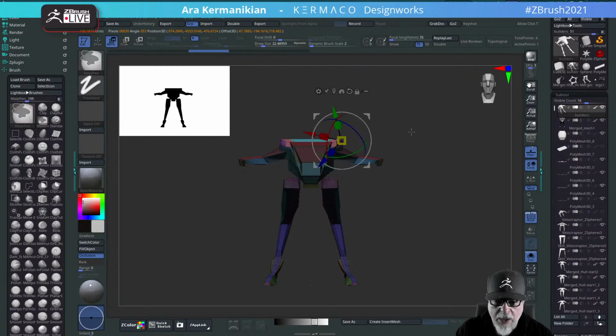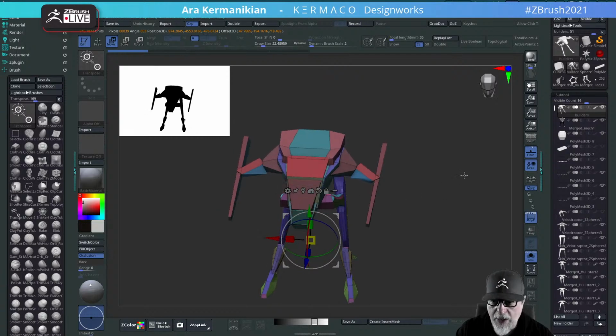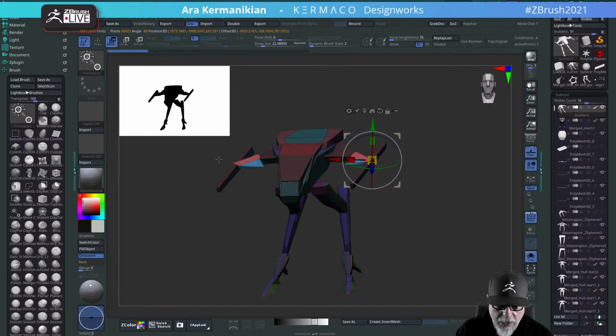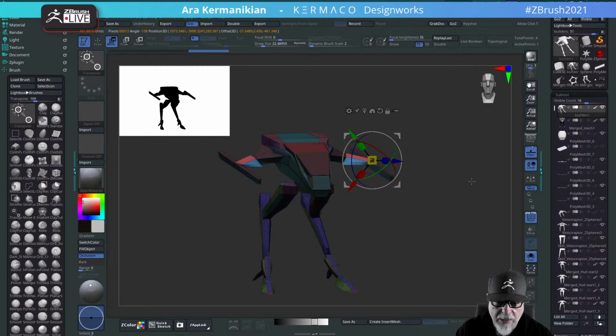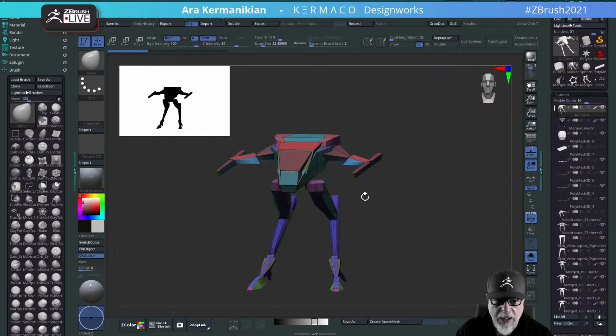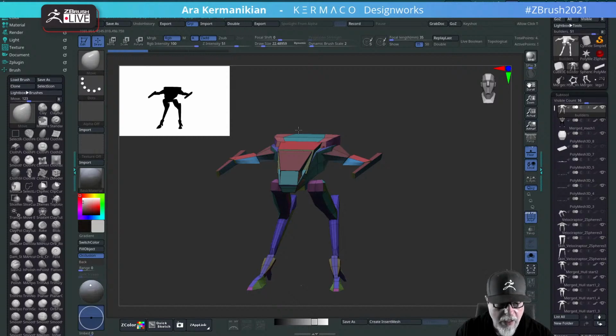If you want to mask certain pieces, move mode allows you to do a move from a certain point. So if you hold Control down and you start moving in a certain direction, you will mask in that direction. That's a masking methodology. But if you just want to mask something and get rid of it, just be in move mode, like with the move brush or any other brush really, and then maybe use the mask lasso, and then you can just choose what you want to mask like this. And then there's no gizmo or anything else getting in the way. Hopefully that answered your question.